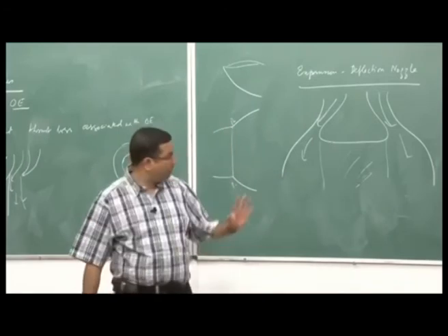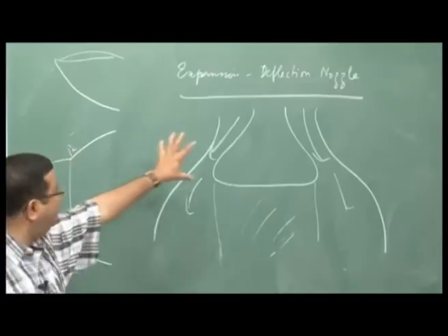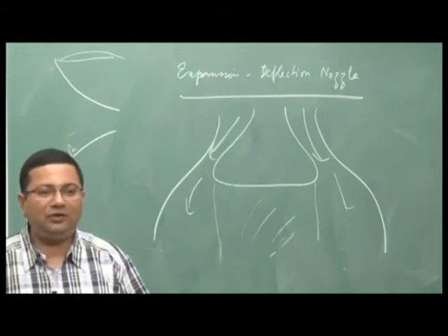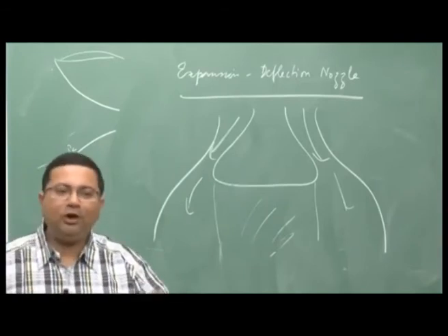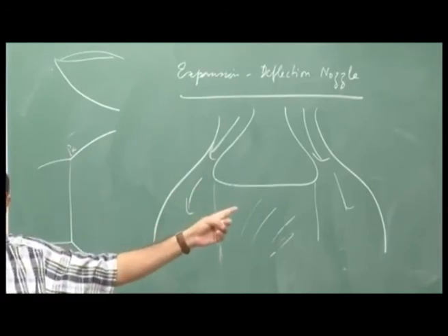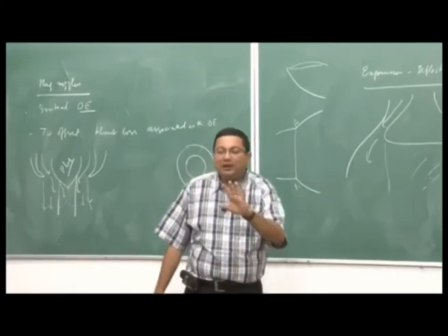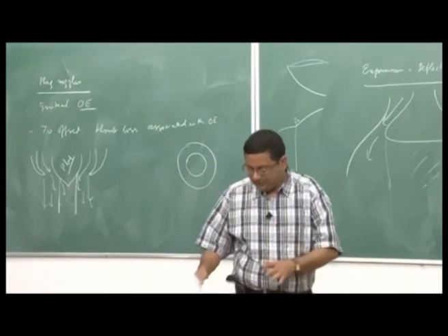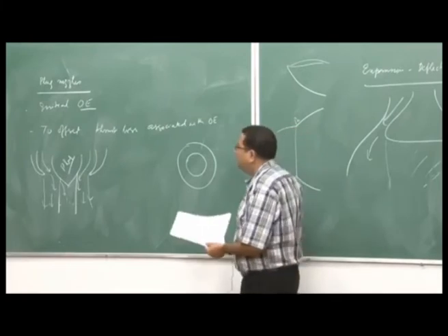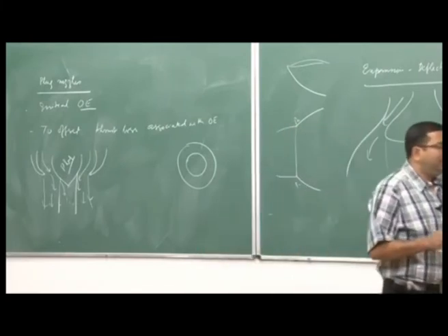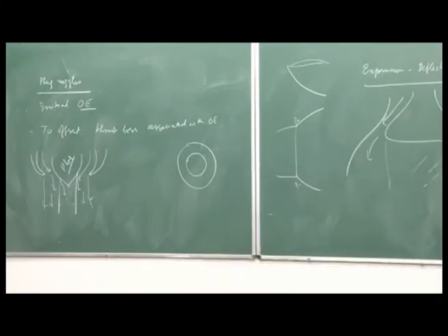which is something we do not want to have. That is why both this plug nozzle as well as the expansion deflection nozzles are primarily for the over expansion case. Under expansion is still much safer. Okay. So, this is what we wanted to discuss about the nozzle flows.